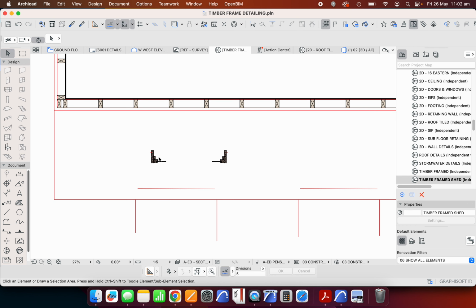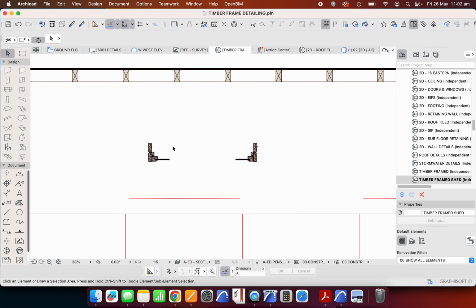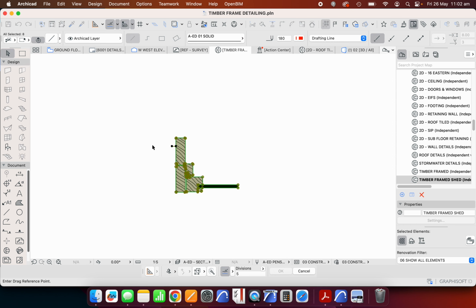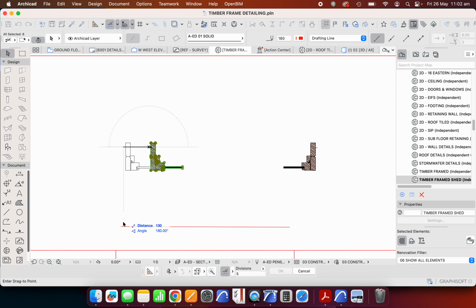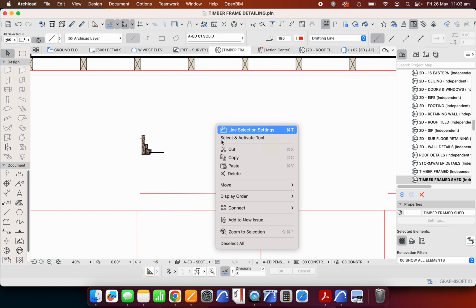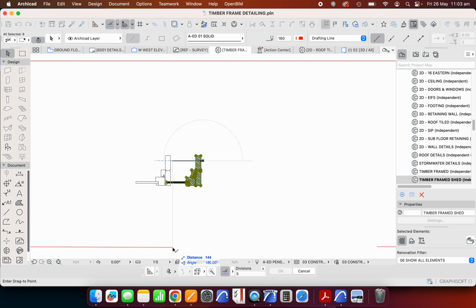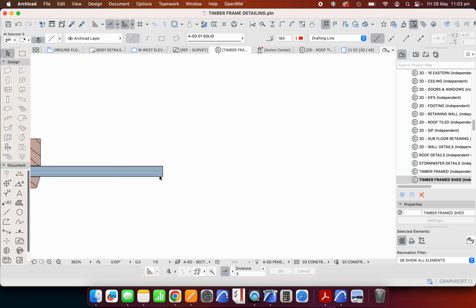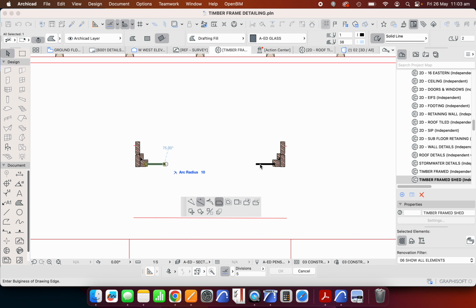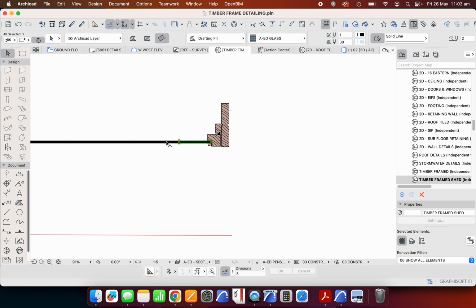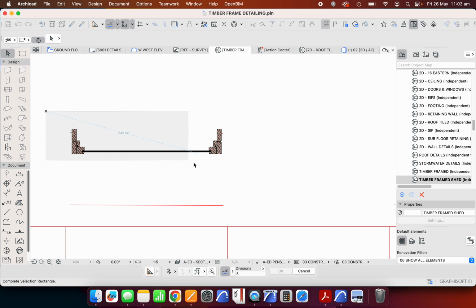And I'm not needing to use a lot of maths, of course. I'm just using ArchiCAD's ability to do equal spacing. Now, I can move these into position based on that. So let's move this back and move this back. That's now representing my window. And of course I want this glass not to be 2 pieces, but 1 piece. So I'll just extend that to be full length, and then I'll get rid of the one that I don't want. And that's now finished.